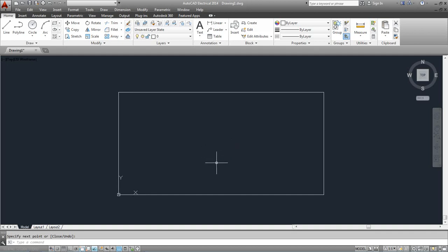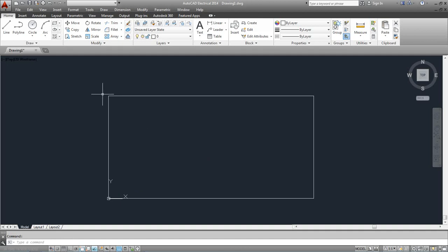So this is how we can make a rectangle with the absolute coordinate system. Just remember one thing in AutoCAD: when you are using absolute coordinate system, the option dynamic input, the shortcut is F12, should be off. If this option is on, then this coordinate system works like relative coordinate system. Except line, you can also make the circle and other commands like rectangle and ellipse using absolute coordinate system.